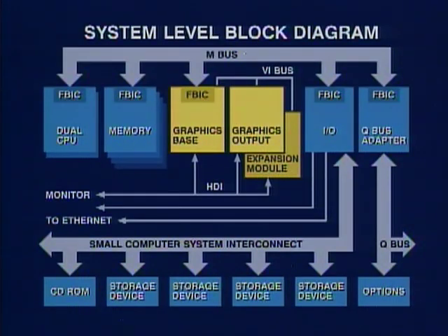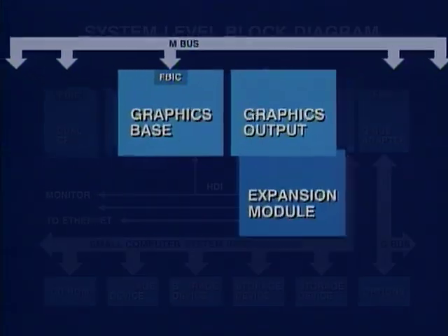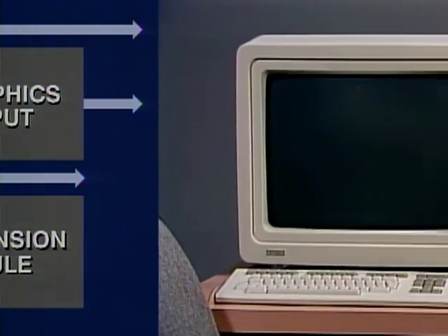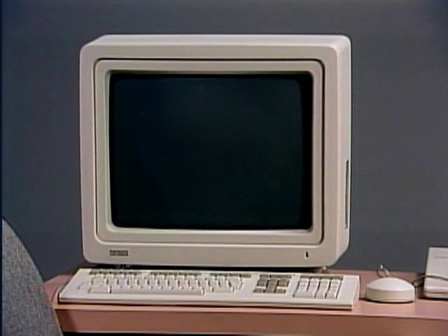In this lesson, we'll discuss the VAXstation 3520-3540 graphics subsystem. The graphics subsystem is a high-performance video subsystem capable of executing both 2D and 3D display lists. It generates high-quality video images. In addition to general-purpose graphics output, the video subsystem provides the primary console port for the VAXstation 3520-3540 workstation.